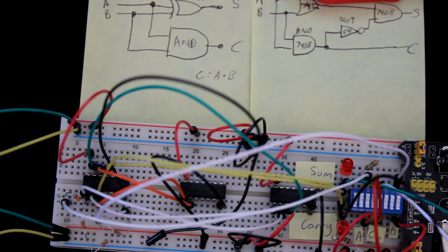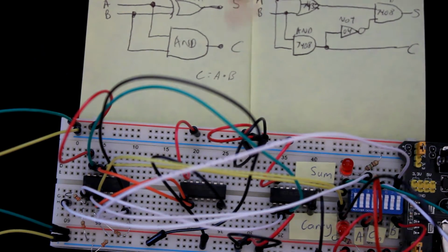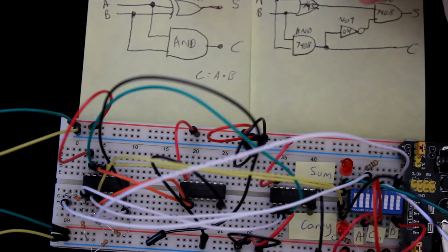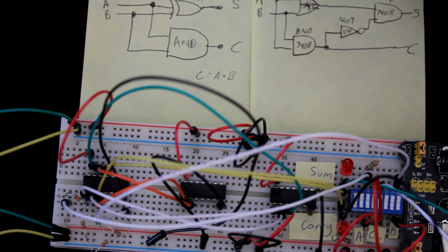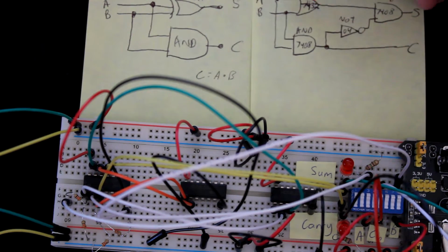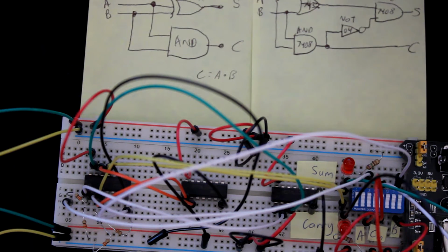Hello YouTube, this is a demonstration of the half adder discussed previously in this video, which I have placed here for reference. As you remember, a half adder consists of an XOR gate and an AND gate sharing inputs, where the XOR gate outputs the sum and the AND gate outputs the carry. However, because we did not have any XOR ICs to work with, I decided to implement this half adder on the right, which uses an OR, not an AND gate, instead of an XOR gate.